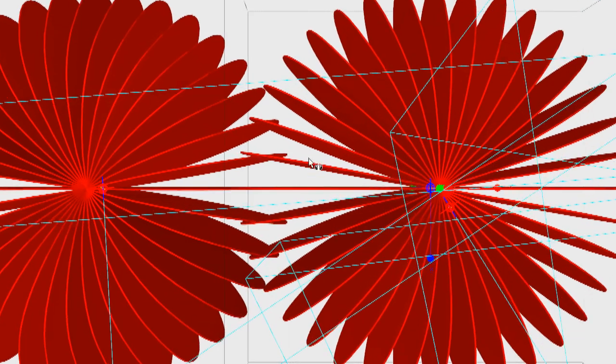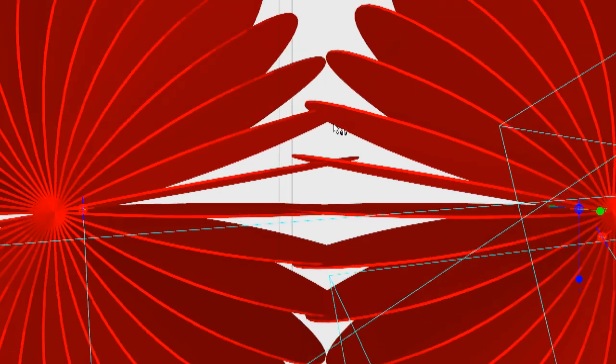These are both vertically oriented antennas. The polarizations match, and the benefit with that, as you can see, is this cross-sectional area here where they join up is extremely large. Yeah, they're sharing an awful lot of the same space, which means we're going to have a very, very good signal.